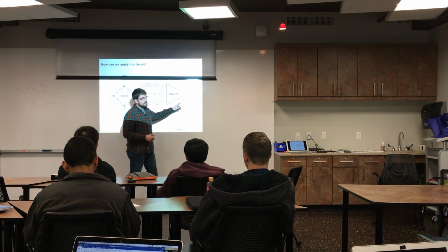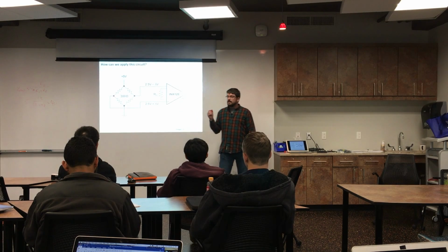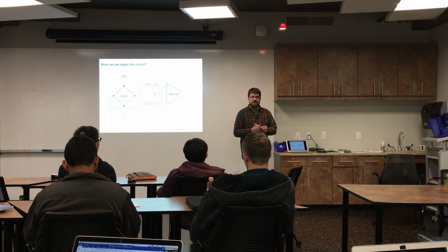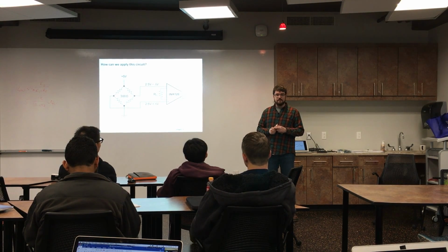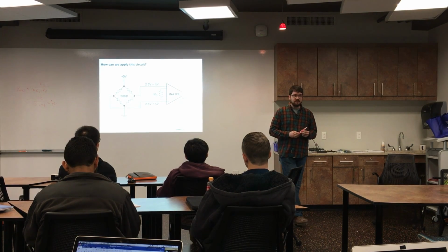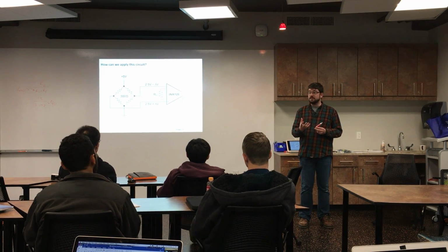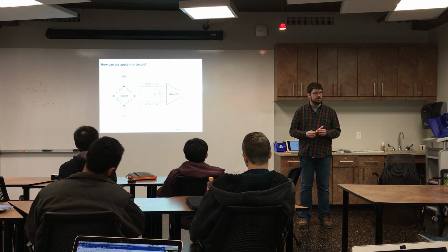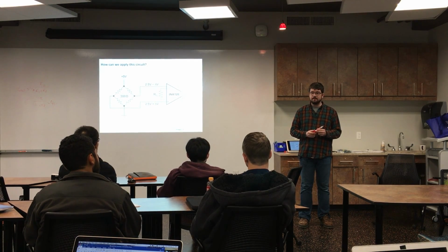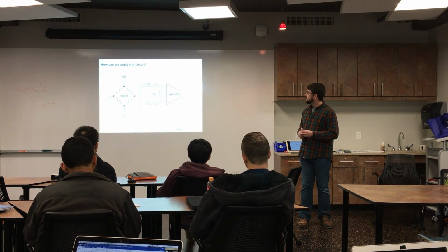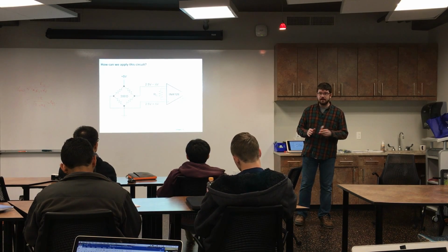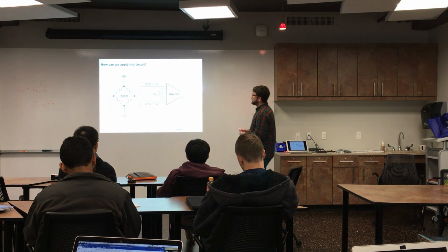So that terminal changes the 0 point for your amplifier, where 0 difference is. You should not have a large offset out of your amplifier, out of your bridge. If you hook your bridge circuit up to a power supply, you should have an offset of a few millivolts, maybe 10 millivolts. If you've got more than that, there is something wrong, and you should find us and look at it. Volts are right out, because that's a huge common mode value that we're not going to be able to get rid of.